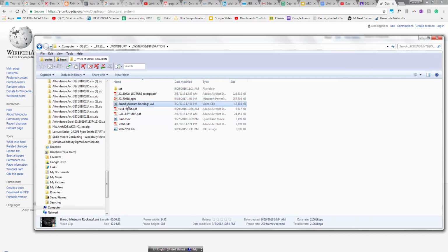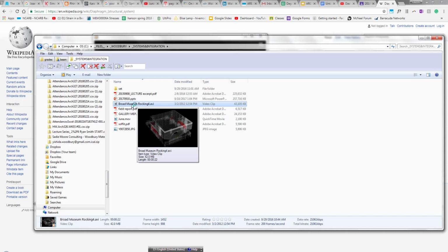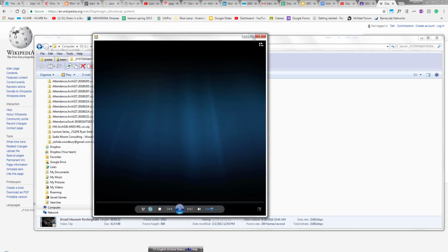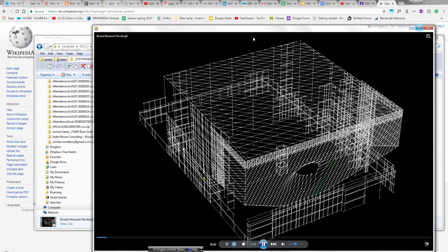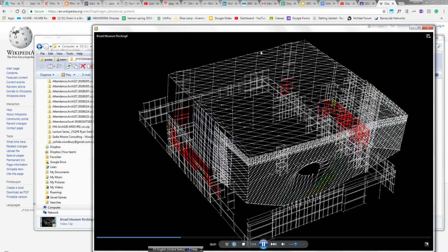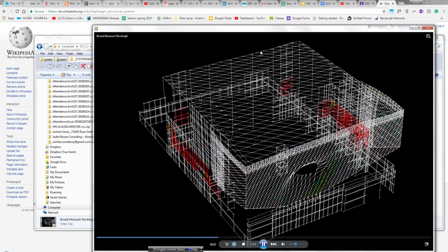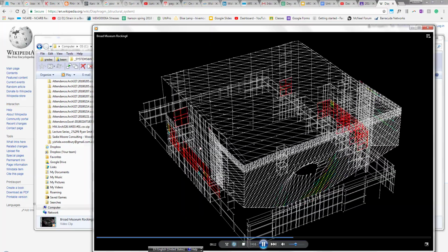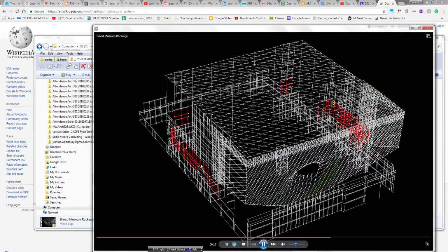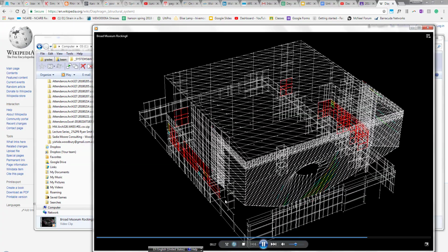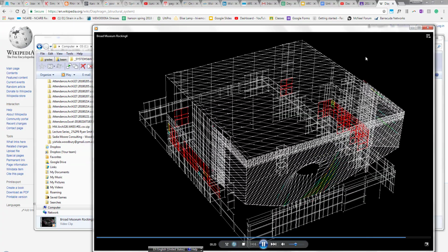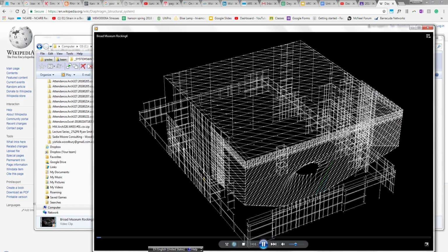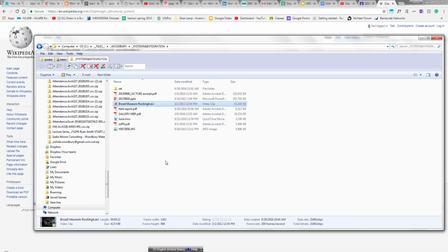So I guess the only fun thing today is this animation, which I got from the structural engineer, but this demonstrates how that happens in a really, really exaggerated manner. You can see how the building is trying to rock back and forth horizontally, but all the forces are actually concentrated to the footing, which is what you want to happen. How that's happening is through the use of the diaphragm and the shear wall, right? So anyway, that's the intro.